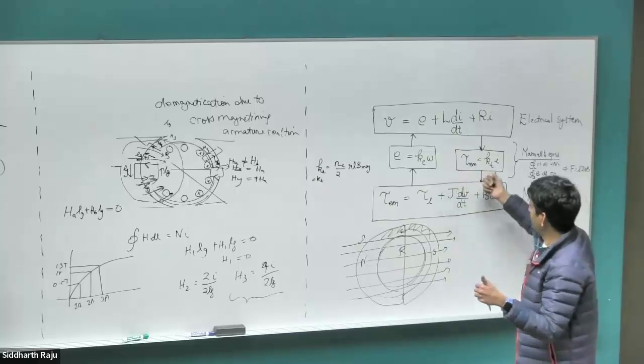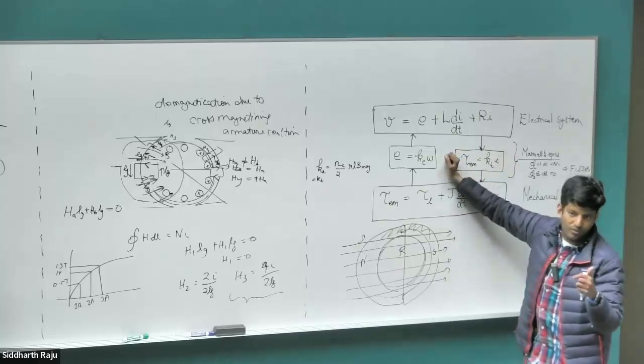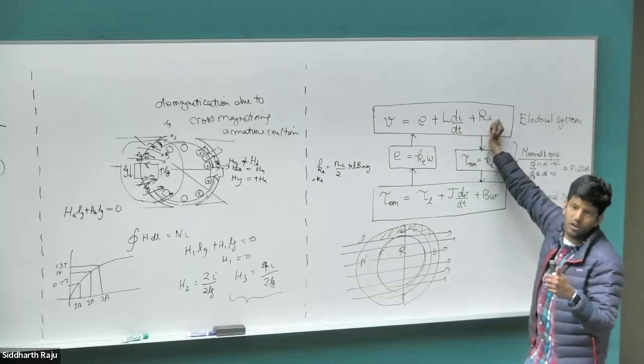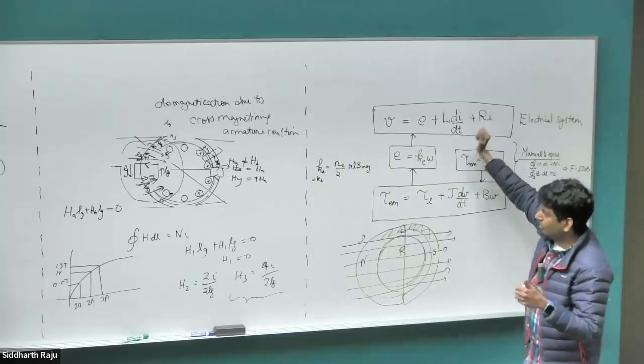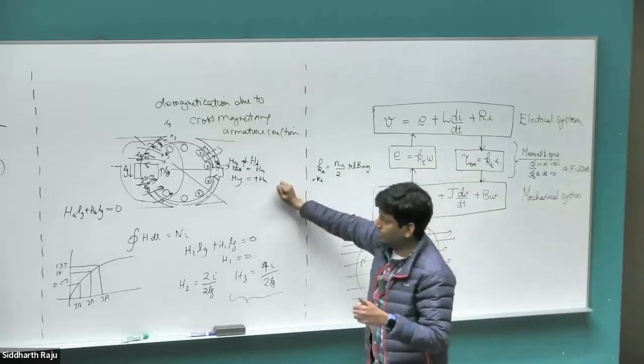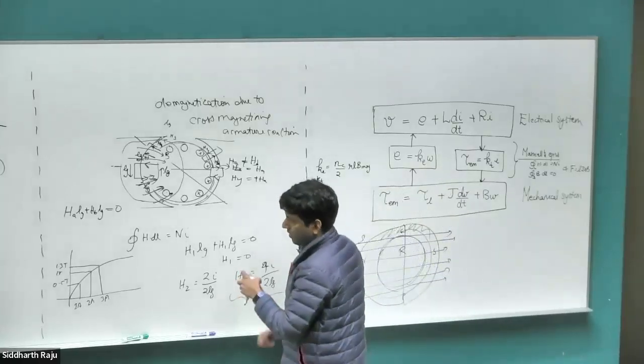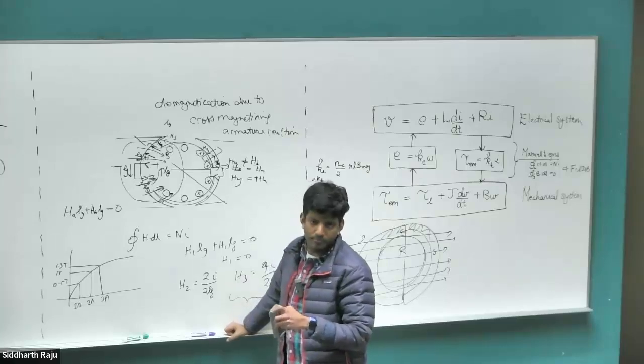That means you would need to push more current to get the same amount of torque. And the problem with pushing more current is you start to have more losses as well because of the Ra component. Right? So this becomes the problem. You start to have loss of efficiency because of this demagnetizing effect. Okay? Anybody has any questions so far? Okay.